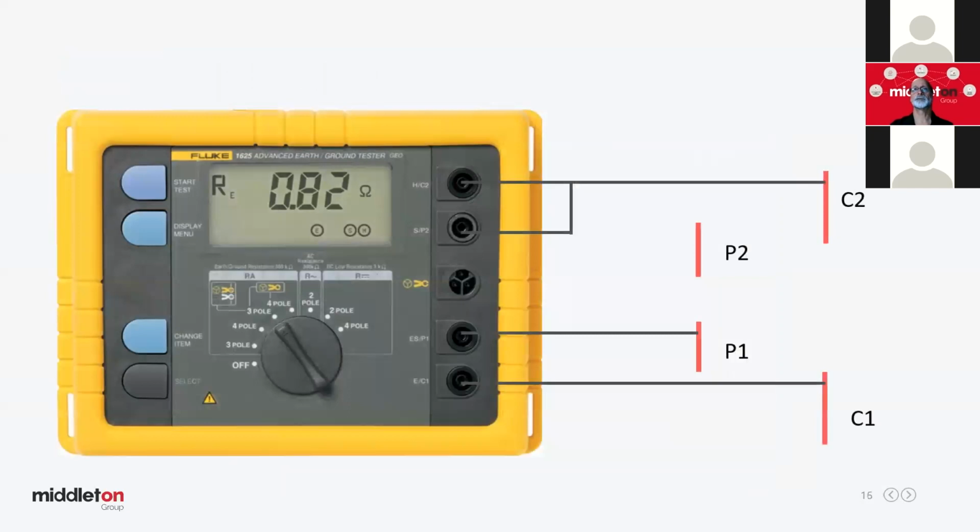So if we do have a bit of a recalcitrant spike, if our meter's normally got warning lights on here, and they'll be flashing and telling you, I've got a problem on the E terminal, which is this one, or the S terminal, etc. I think this one's flashing at the time. It's off when the photograph was taken, so it's telling us that yes, here's got a problem. So you go out and you tap on that one and put some more water around it.